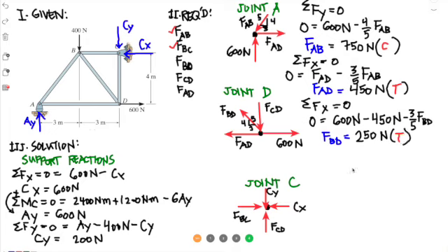Okay, 3 forces. So what's next? We need to find FCD, and as you can see, we only have 2 components here, so summation forces y equals 0. So 0 is equal to, what do we have? We have the positive component of FBD, which is 4/5.